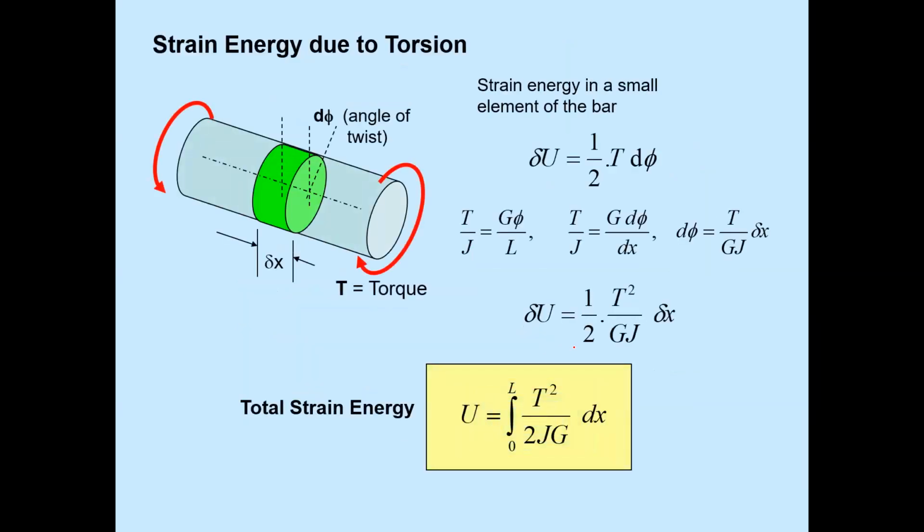Now, there can be bending in any member, there can be an axial force in any member, there can be a direct force in a member, or there can be torsion in a member. So due to each and every force, some amount of strain energy is stored in that member. So now the second case is strain energy due to torsion. This is a hollow pipe type structure shown in this figure. The torque T is applied in this direction. The deflection of the member is delta x.